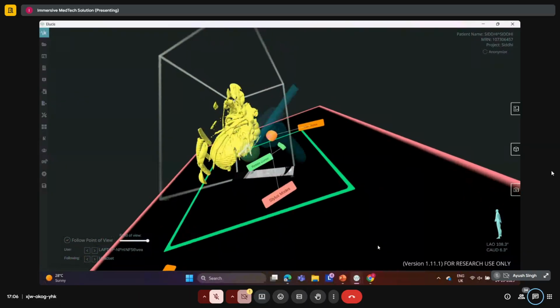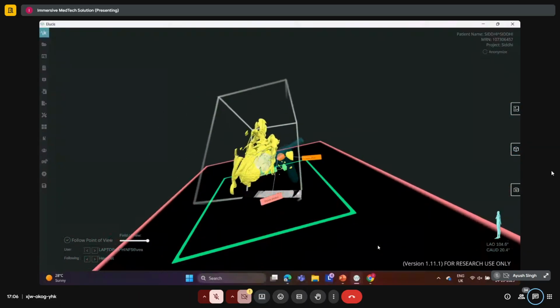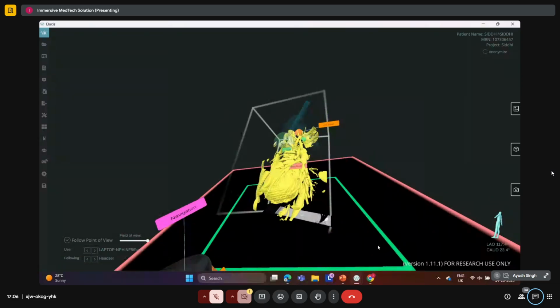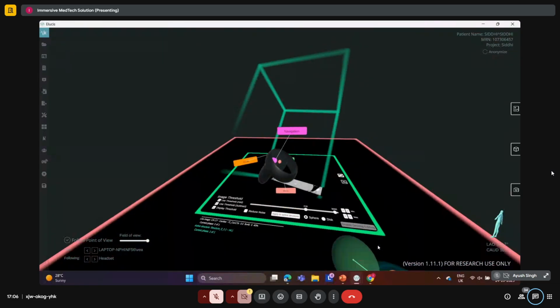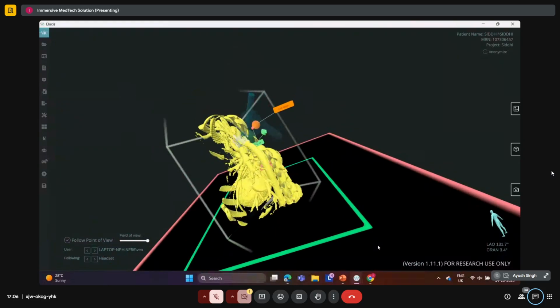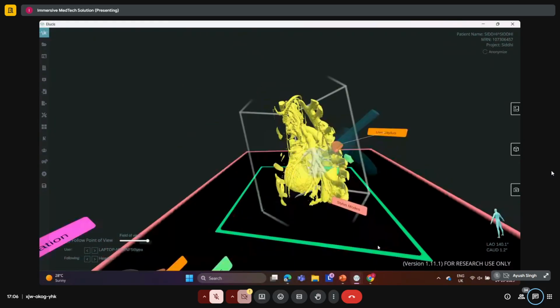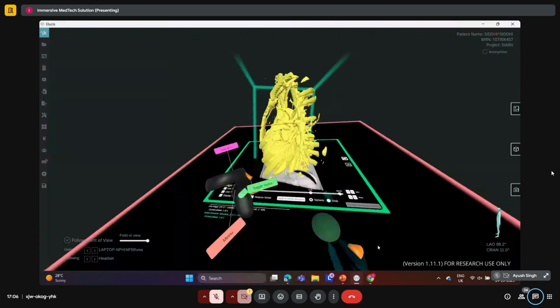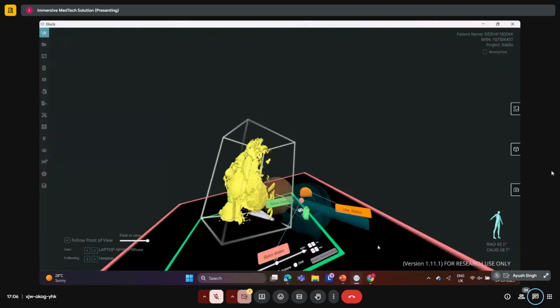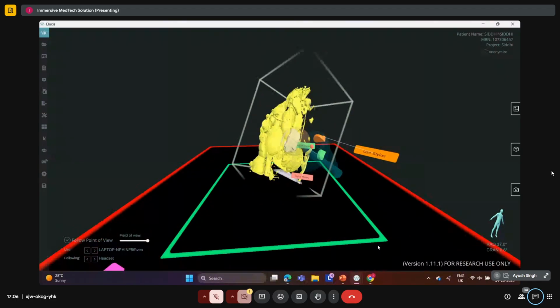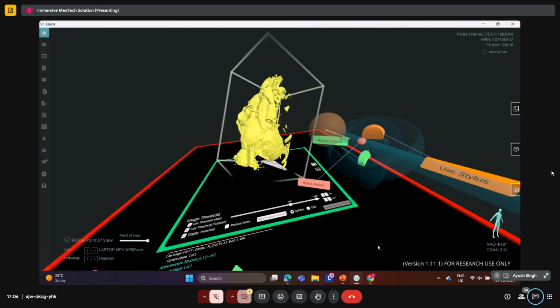So we can easily do the segmentation. We can increase the brush size to do it a little bit faster. But one might question that there are a lot of nearby regions that are also getting highlighted. So this is how the operation would work. Once we have generated the model, and we are finished with it, the color goes from green to orange. And now, whatever part is undesired, we can just remove out. I'll just reduce the brush size.